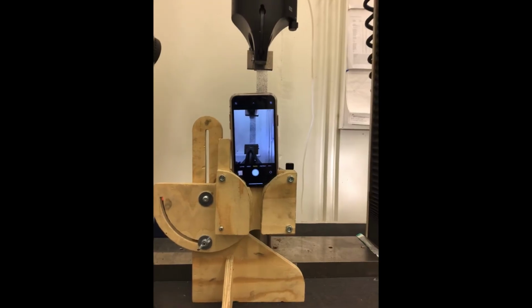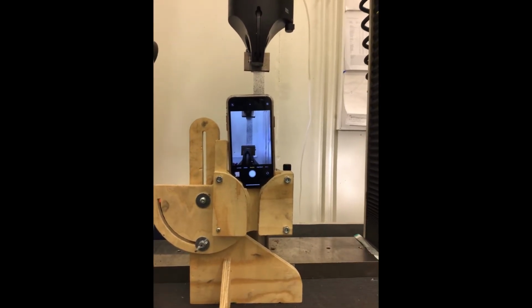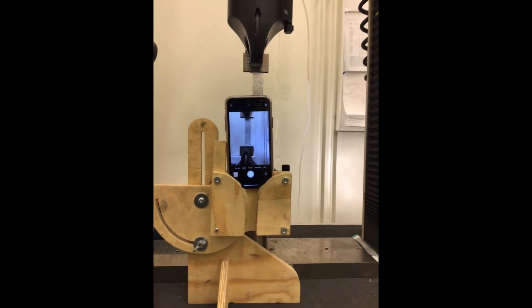I have now put the specimen on a flat surface and used a long press on the paint can to have a random speckle pattern. This was good enough for me. The test specimen is now mounted on the tensile test machine. I used a custom-made mobile holder to record the video. Adjust the focus of the video directly on the specimen. You can use any other way to hold the mobile.